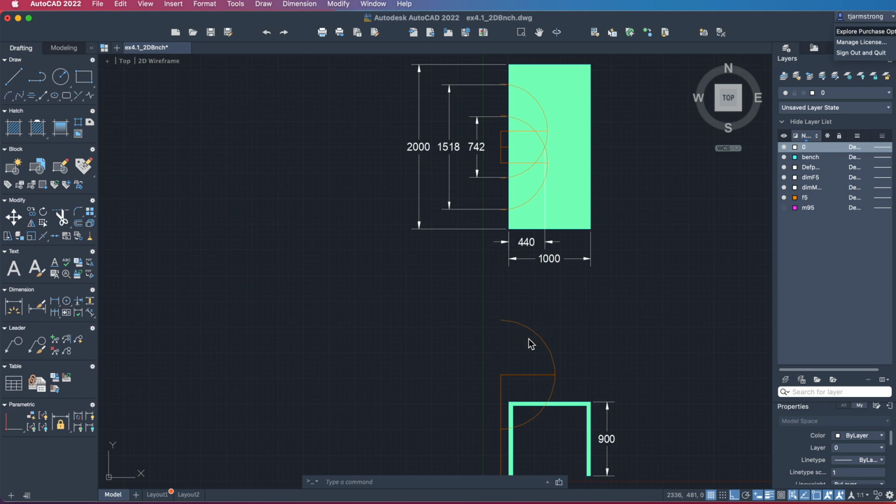And we just finished an exercise where we created top views and side views of the worker standing at a workbench that's 0.9 meters high or 900 millimeters high, and has a top view size of 1,000 by 2,000 or 1 meter by 2 meters dimensions. And then we've used these stick figures to generate arcs to show how far somebody could reach and actually touch something on the surface of that bench.